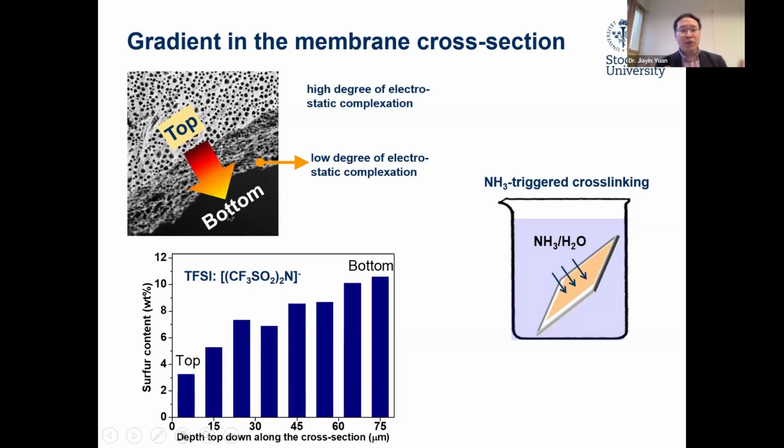Now you have a porous structure and a cross-linking density gradient, where the top part is highly cross-linked and the bottom part is less cross-linked. In contact with acetone, since acetone will swell the membrane, the bottom part captures more acetone and the volume expansion would bend the membrane with the top surface inward. That explains the bending behavior.